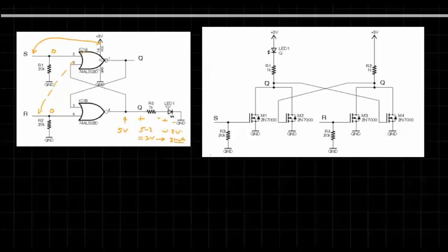On the right here, this is the second circuit you're going to build, and it is also an RS flip-flop, but it is implemented discretely. So I wanted you to experience being able to construct a memory circuit using just discrete transistors. So this right here is a NOR gate, okay? And if you think of it, if either input of this, if this input here or this input go high, then that respective transistor goes on and pulls this output to 0, right?